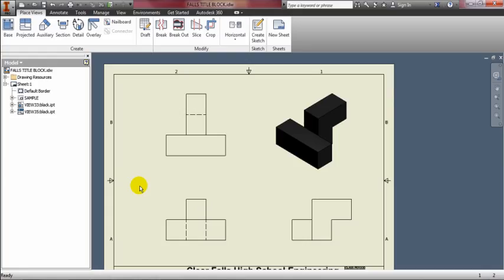So the first thing that we want to do is establish how many lengths, widths, and heights that we have. Well, the lengths can be seen on both the top view and the front view. I have one length for my overall. I have a length between this line and this line, so this distance. I have a length from here to here, so that's 3. And I've got a length from here to here, so that's 4. I have 1 all the way across, 2 here, 3 here, and 4 here. Which means that I have to give 3 dimensions.